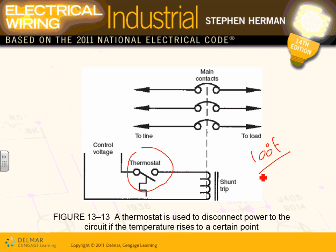100°F. If I want to set the circuit breaker to trip if the temperature in this area reaches 100°F, I put a thermostat right here, and I bring a line to, let's just say, 24 volt DC, or 120 AC or DC. You put it into the thermostat, it will close, energize this coil, and this coil will open the shunt trip, which will open the circuit breaker if the temperature reaches a predetermined value.